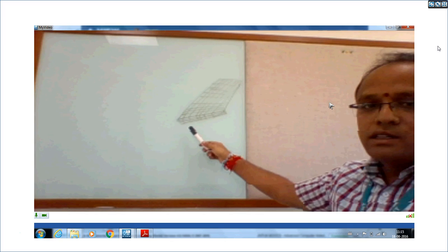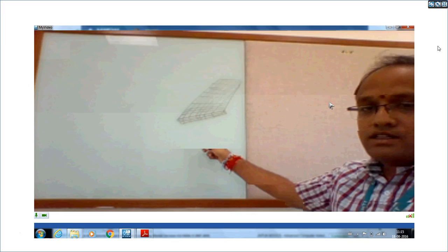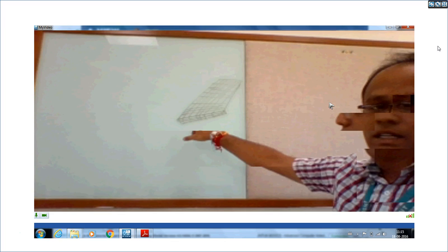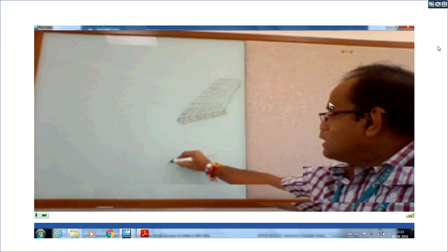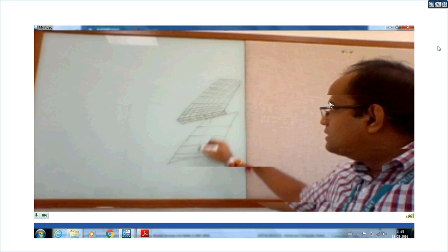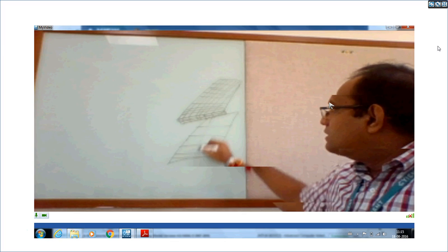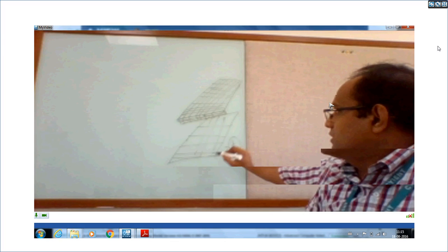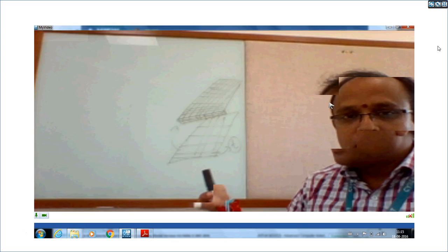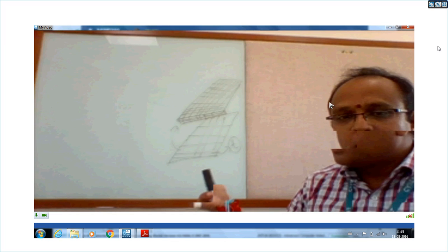For that purpose, these shell elements are derived so that we can get results with great accuracy. We also cannot put too many elements across the thickness. Whereas if you model with a shell element, it is very simple. We can extract the mid surface, model this area, put elements, and assign the thickness. That will represent this component. One important thing is that it reduces the problem size and gives results with greater accuracy.